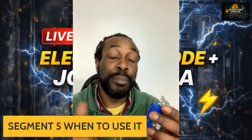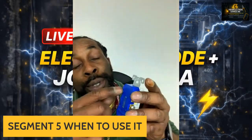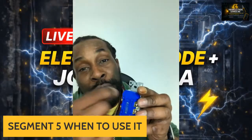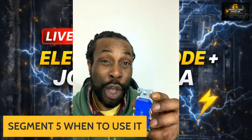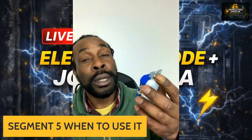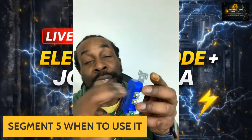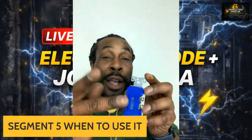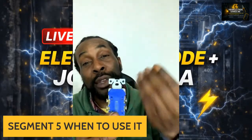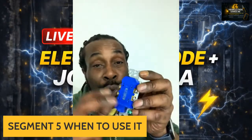Again, you have to position your wire in the correct manner so your wire is not moving when you put it in. It all depends on how you actually install the receptacle. When you backstab into the back of here, you have to guide your wires accordingly and tuck them in, so there are no loose connections.